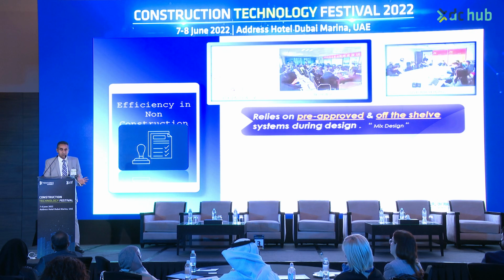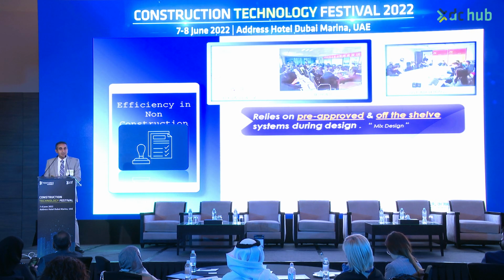So can the contractor start? No. The contractor still has to develop shop drawings. And this shop drawing has to go back again to the engineer to approve it, and he has to wait. Does the approval of the engineer relieve the contractor from his liability, or bring the design liability back to the consultant? No, the accuracy of this shop drawing will still remain with the contractor.